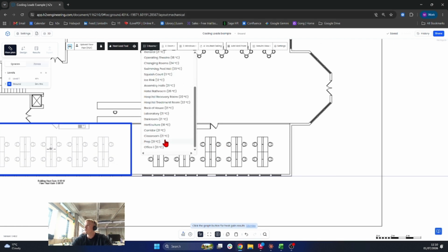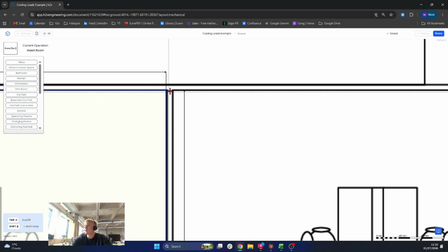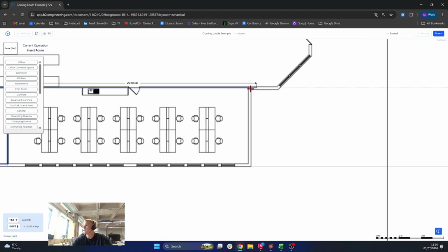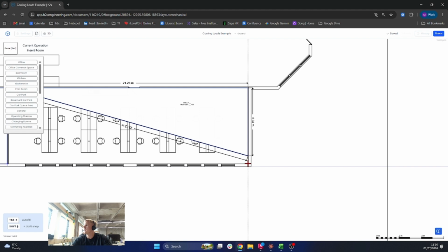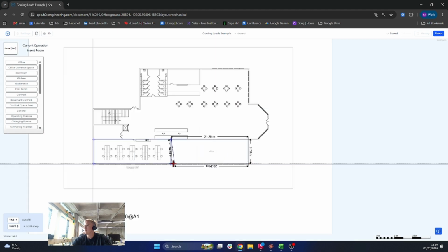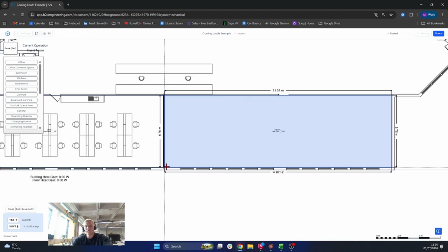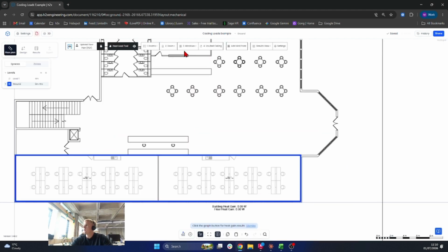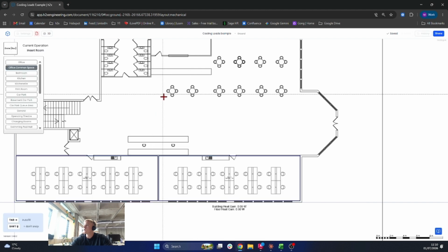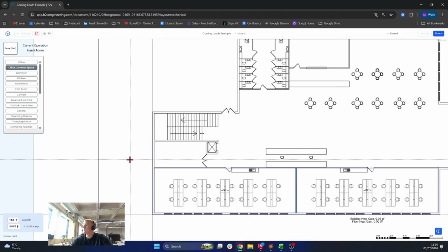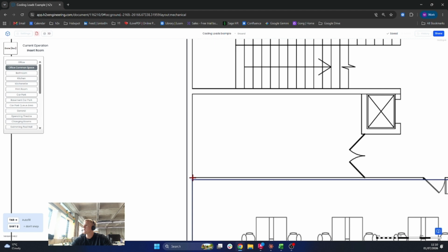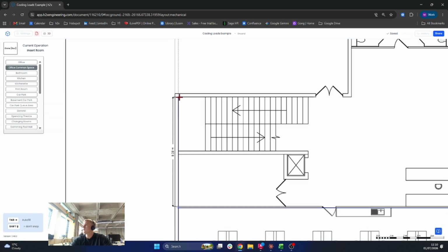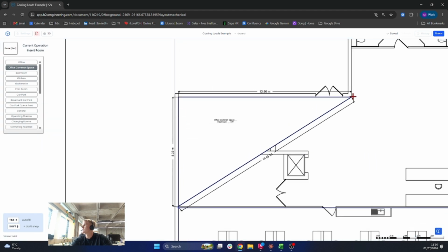When you draw an additional room next to one that's already been marked out on the software, H2X will automatically pick up the internal wall and differentiate it between the external walls. So you can see there, external walls are blue, internal walls are currently grey. Now, if I go up to the room tab at the top here, I can draw in our office common space and do a left click here to start, left click here, bring that across.